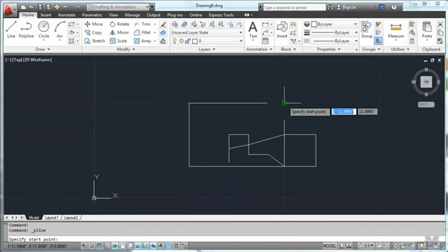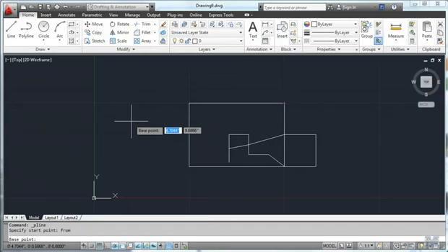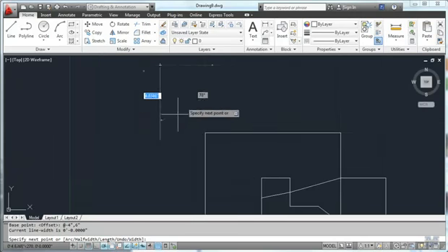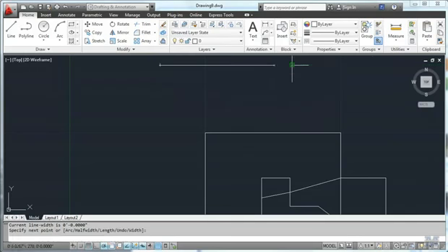Try a different way. So I haven't started to draw anything yet. Type the from command. I'm going to go from this point up here, so I'll just left click there, and I want to offset. I'll use the @ symbol to make sure that it's a relative offset, and we'll go -4 inches and comma 6 inches up. Try that, and then that puts my cursor starting right up there, so it just automatically went up to that point. I'll pan up a little bit to see how that looks, and then we could continue drawing from there.